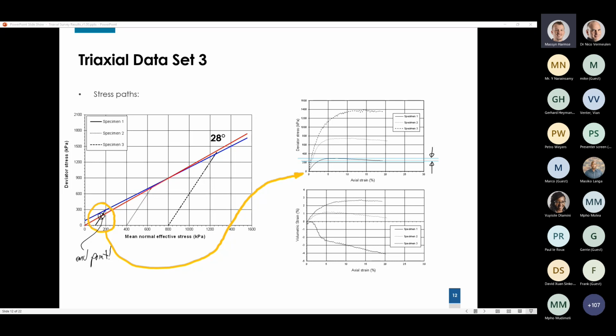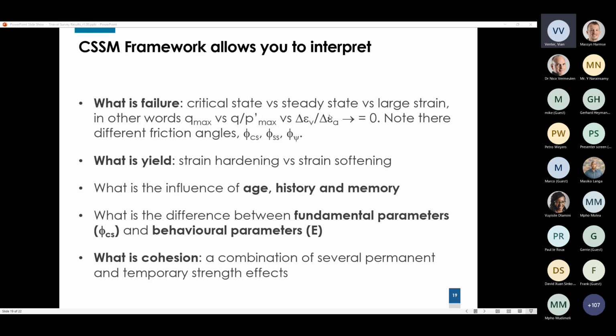Okay, Vian, I hope it's going to be a quick one. It will be. It follows up on the previous question. Specifically, it all depends on how accurately the SG was calculated. Especially with clay samples, you get some labs that still do 2 hours and they don't get the right SG, and that influence on the void ratios that you get from triaxial specimens can be massively influenced. So just a comment on that.